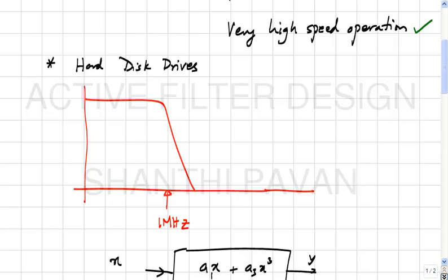Okay. Now, let us say the input to this filter which we have built is a 2 megahertz tone here and a 3 megahertz tone here. You understand? If the filter is absolutely linear, what do you think will be the output of the filter? It should be 0. Why? Because 2 and 3 megahertz are in the stop band of the filter, they will get eliminated by the filter.